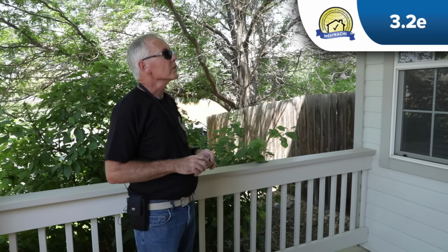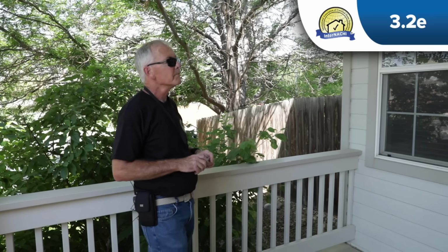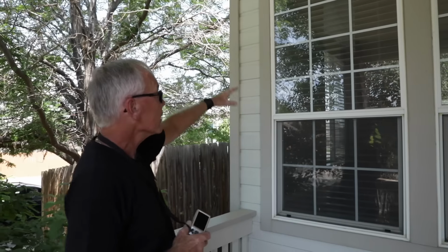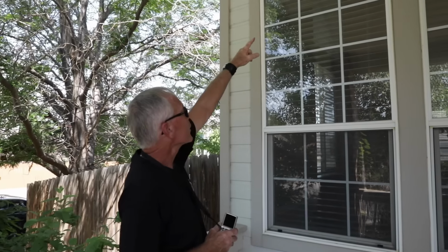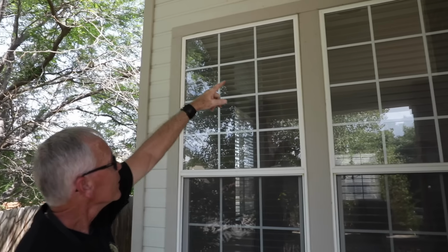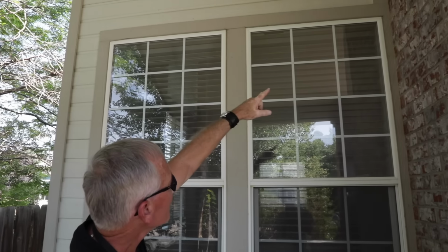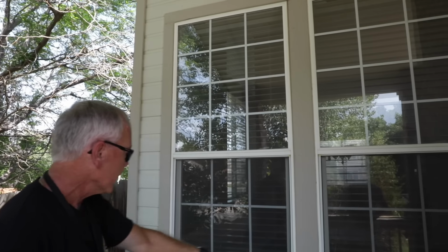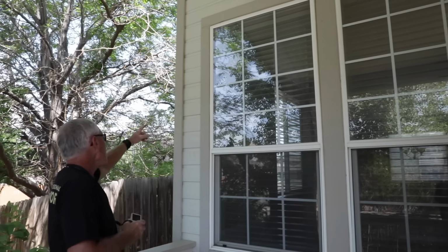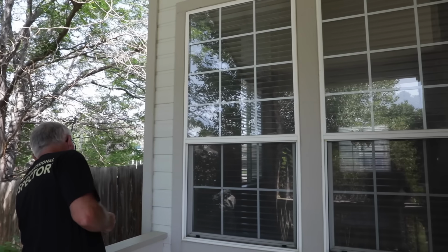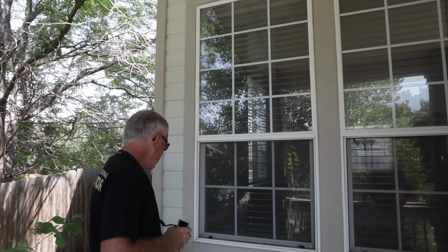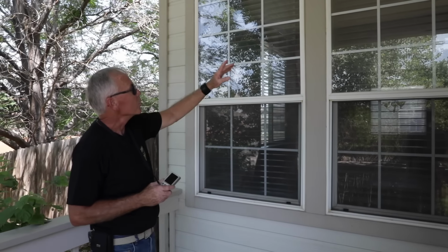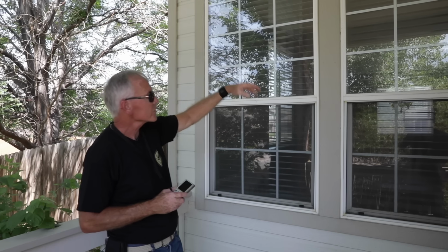Okay, now we're going to move on to the flashing and the trim. And so what I'm going to do is just start here at these windows on the front of the house. And what I'm looking for is the flashing above the window and all the trim that comes down on the corners and around all the windows and the doors. So I'm looking for that. I'm going to be looking for potential missing caulking, water damage, loose fasteners or loose nails.